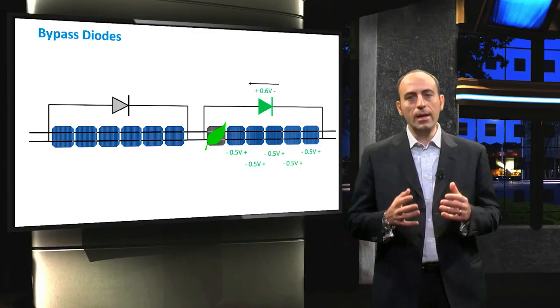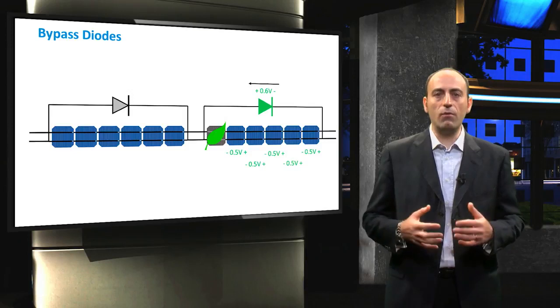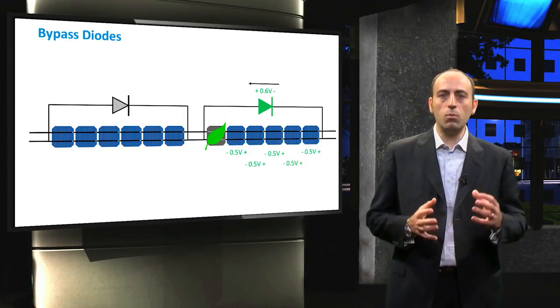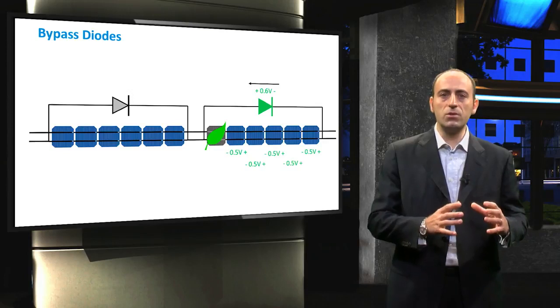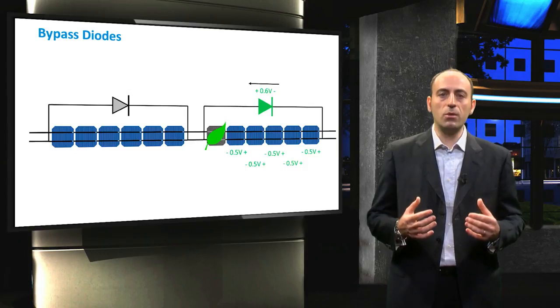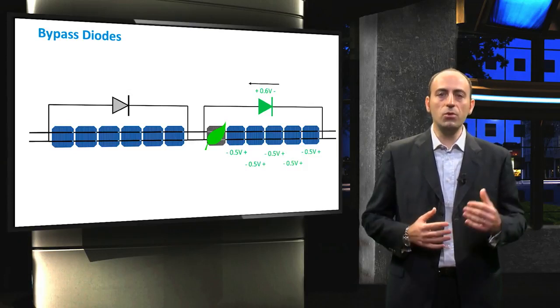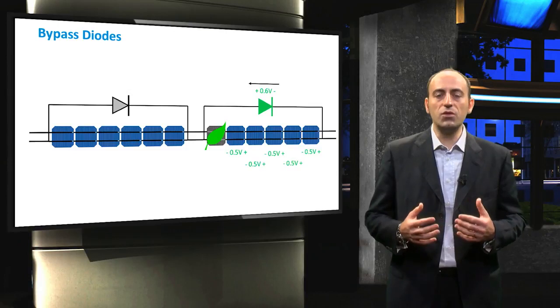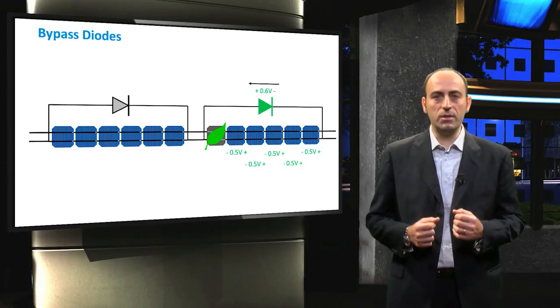Until now, we have seen series and parallel connection among cells within the module, but note that you can also have modules that are connected together in strings and then in arrays. So we have to project the same type of problems discussed at cell level to module level. Let's imagine a very large PV plant of hundreds of modules. It may happen that one part of the plant is partially shaded by clouds, while the other is still well illuminated. As a consequence, partial shading without bypass diodes generates a very huge imbalance that, even for a few seconds, can hinder the lifespan of the complete PV system.